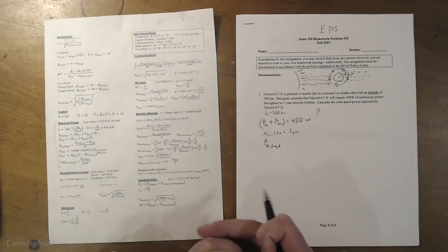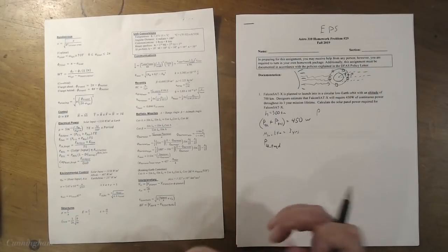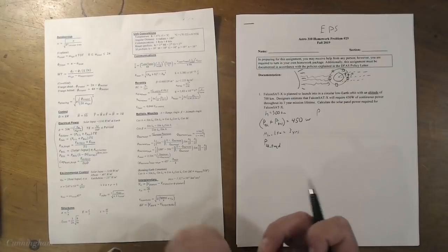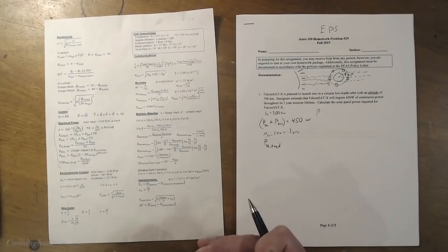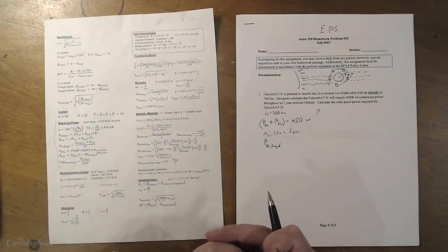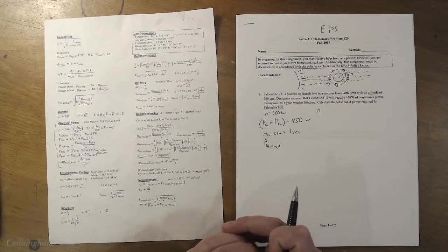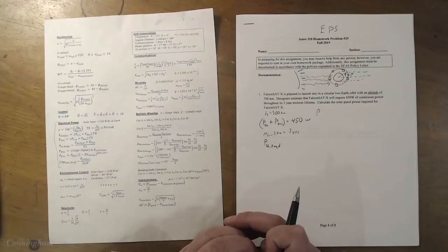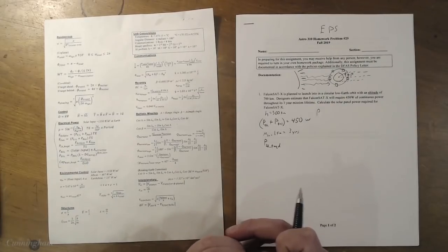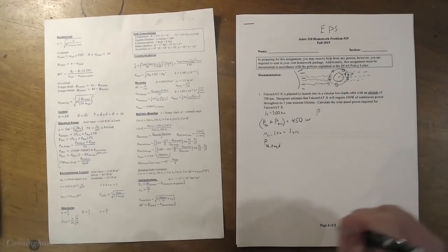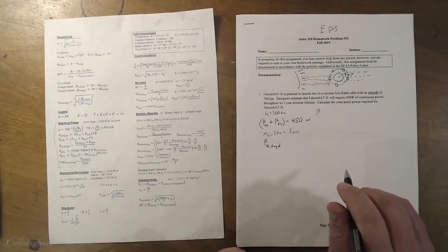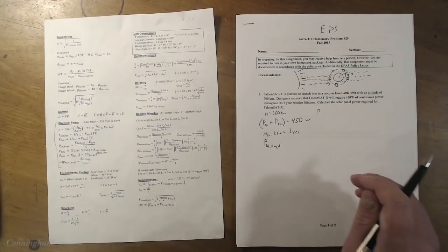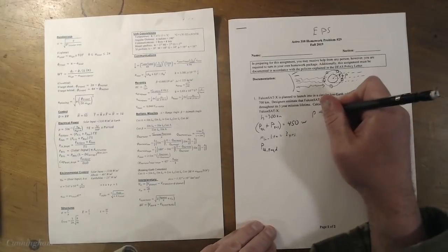Remember, the Earth is tilted 23.5 degrees with respect to the sun. So there's only a couple times throughout the year where GEO satellites will even go behind the Earth. But LEO satellites are a totally different story. This is a common occurrence for most LEO orbits. So, how much, in terms of a fraction of time, do we spend behind the Earth, which means how much time do we need to run on batteries and keep the mission going? That's what rho is going to tell us.